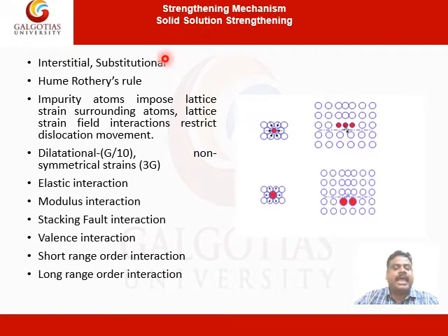That is, one atom substitutes the lattice site of another atom, which is known as substitutional solid solution. In case of an interstitial solid solution, the smaller atoms like carbon, nitrogen, oxygen go and occupy the interstitial positions of the already existing parent element, thus forming an interstitial solid solution.